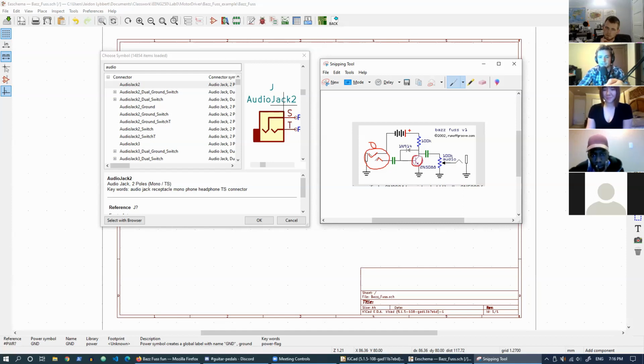The transistor amplifies and also heavily distorts. If you take microelectronics, you can kind of understand that. And then there's a battery for the bias current through here that provides the biasing. And then you take the output right here. So you have the coupling and decoupling capacitors, and you can change those.